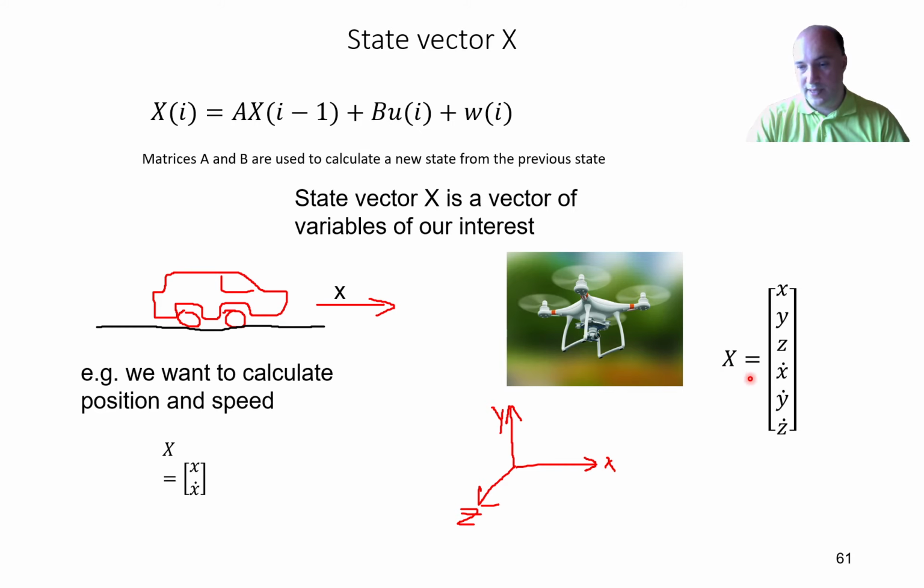So I will take the positions and speed from accelerometer, gyroscope. We will extend it with magnetometer, we'll extend it with barometer. So you will see that this vector x will have, I don't know, maybe 18 columns, and it will be like a very large variable, really complicated, but in terms of calculation it will be still our code that we will see today without any changes at all.